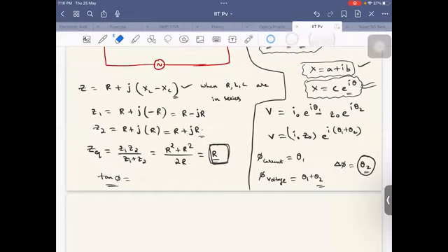Actually when it is this form, from here tan phi is written as XL minus XC by R. So that implies from here also I can write cos phi. Cos phi is nothing but R by under root of this square plus this square, which is nothing but impedance magnitude.